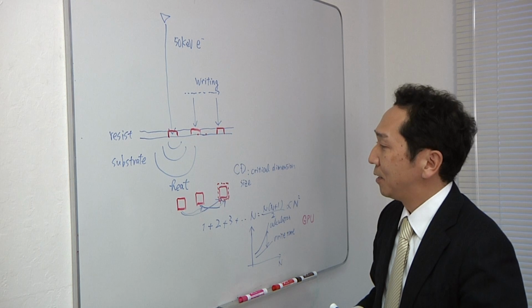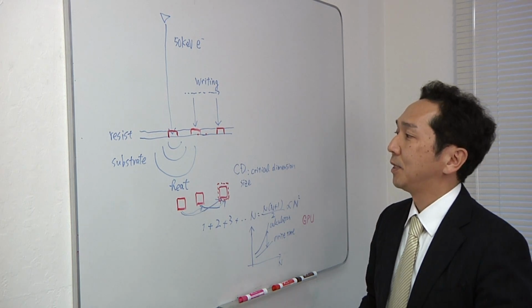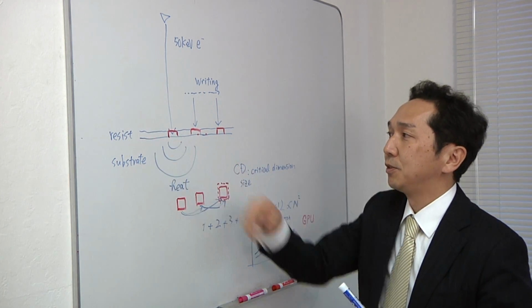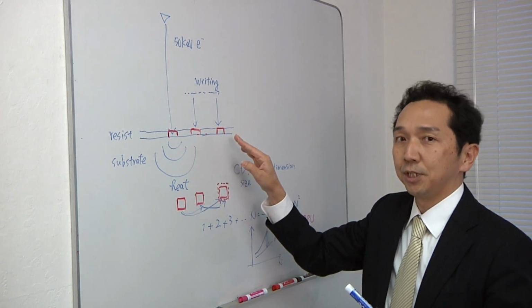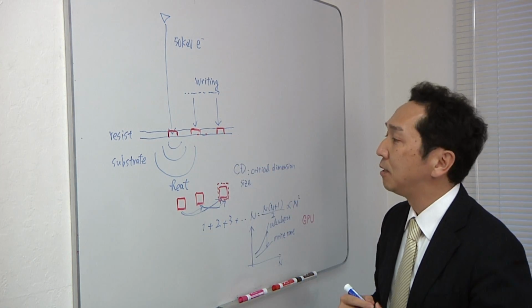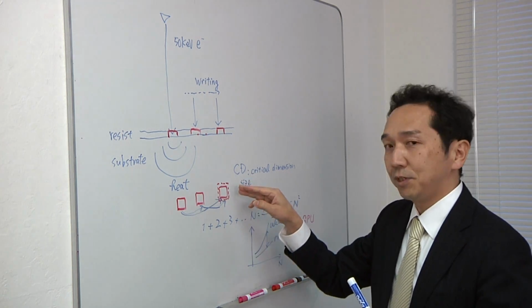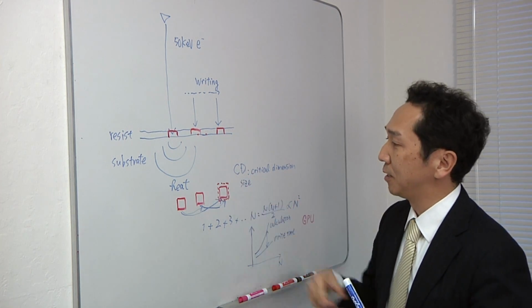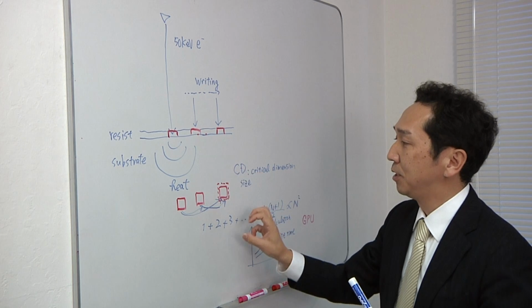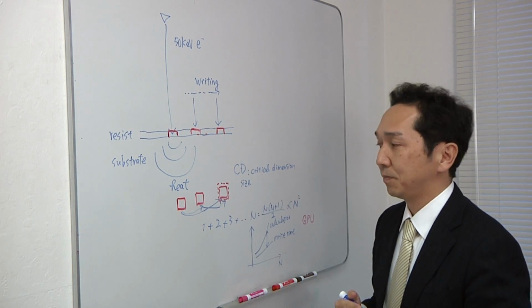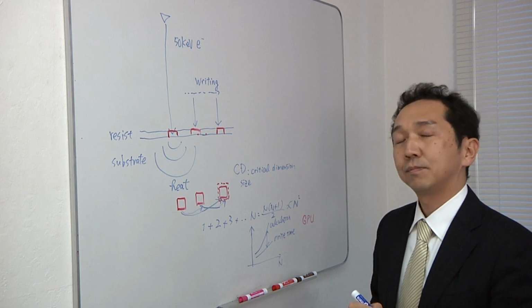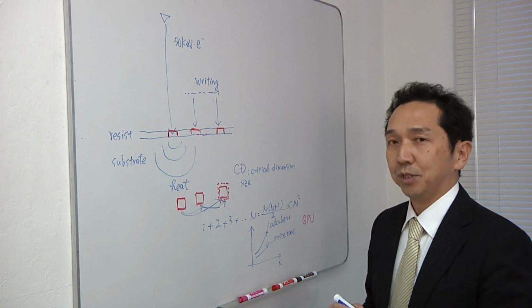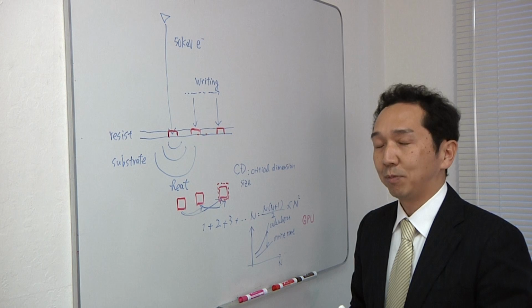What sort of problems does this cause when you start getting that kind of heat buildup? Yes, as is the nature of resist, it has higher sensitivity to electrons at higher temperature. And higher sensitivity means that the size, or the CD, critical dimension, of the pattern is affected by the temperature, to have, in this case, bigger size. Is that just a function of normal expansion? Yes, it's basically a linear correlation between temperature and the size of the pattern.